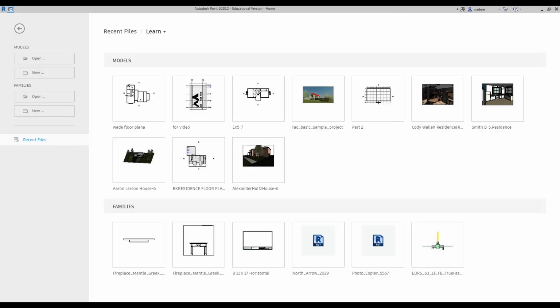In this video on poured in place concrete, we are going to again start a new project. We're going to add datum elements such as levels and grids. We're going to add concrete columns that establish the base of the concrete structure. We're going to create the foundation elements of the building, including the walls, wall foundations, and footings under the columns. And then we're going to add the beams and the beam systems to complete the structural framework and add floors. That sounds like a lot, but in Revit, it makes it very easy and fast.